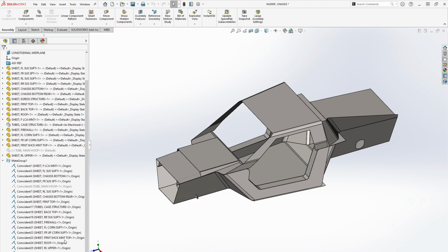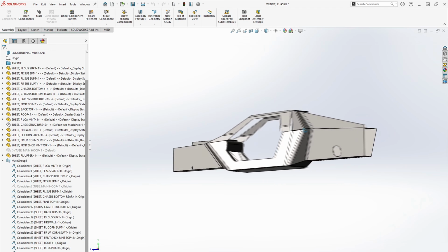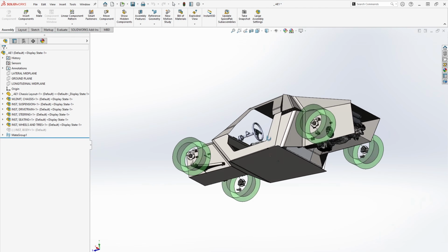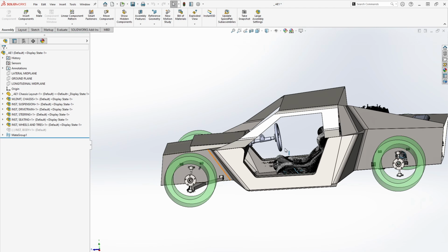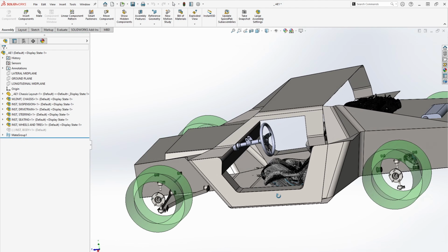They're drawn using those 3D sketches from the root file that then turn these into sheet metal components, or at least surfaces maybe first, then sheet metal components, and they're all done in reference to each other. You might be asking yourself why? Why do all of this top-down design? Why take all the time to develop this system and these structures and things like that? And the reason is for rapid design change and new part implementation.